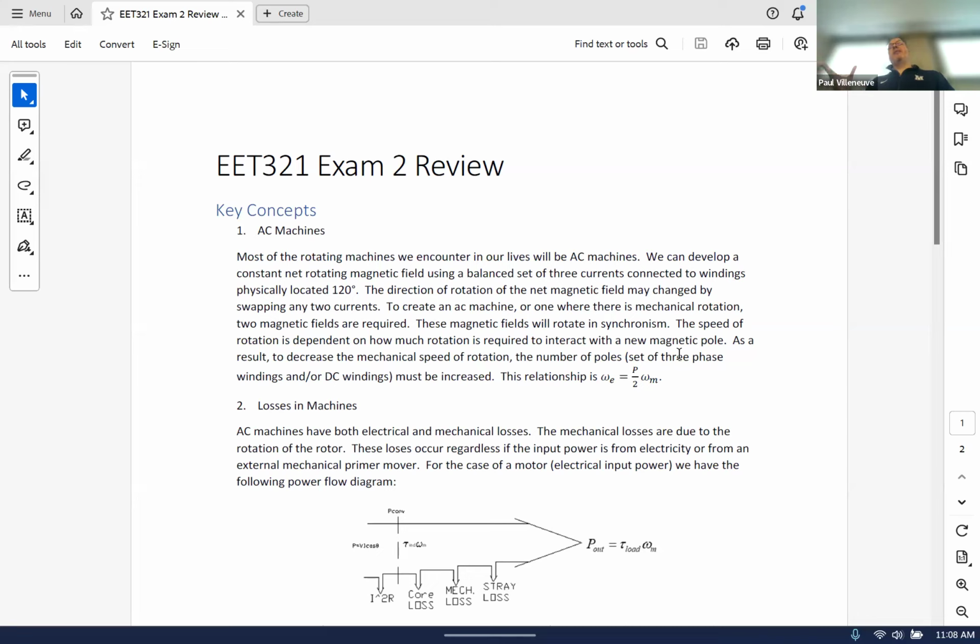Now, theoretically, if you were being on the cheap and you wanted to go ahead and do that, you could probably do that, but that motor is not going to last very long, because the whole advantage of having 3-phase is you get that 1.5 B sub M. If you have 2 phases, you don't always have the 1.5 B sub M. It's going to vary up and down all over the place. So you're going to have a motor that vibrates.